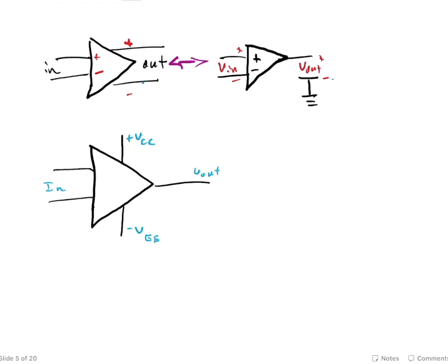And one of the things that I will often do when I'm troubleshooting with you is get your probe and get you to touch your probe right on that pin right there, and then right on this pin down here at VEE, to see that voltage, to make sure that you've actually got it attached and turned on, because it's really easy to think that you've got something turned on when it's not. This is the real thing. This is reality for the lab and simulation.